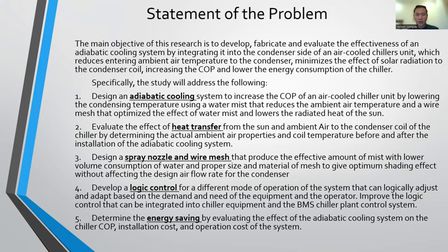Third is to design a spray nozzle and wire mesh that produce the effective amount of mist with lower volume consumption of water and proper size and material of mesh to give optimum shading effect without affecting the design airflow rate of the condenser.